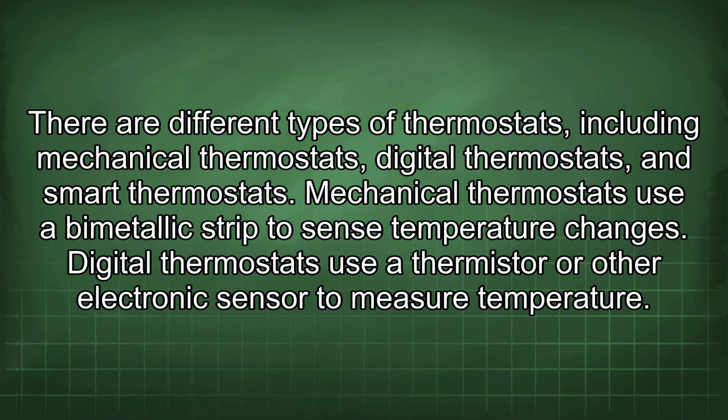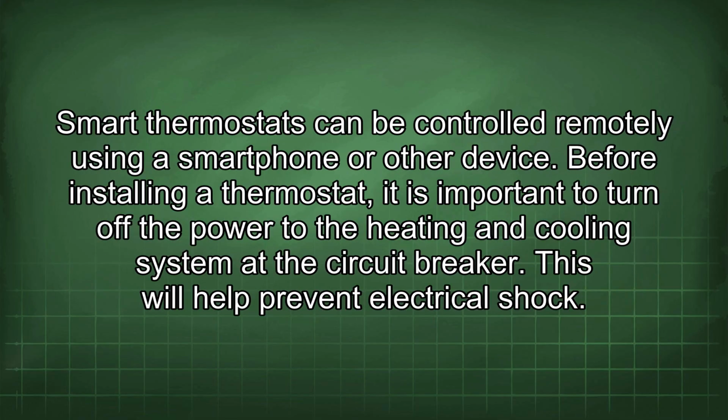There are different types of thermostats, including mechanical thermostats, digital thermostats, and smart thermostats. Mechanical thermostats use a bimetallic strip to sense temperature changes. Digital thermostats use a thermistor or other electronic sensor to measure temperature. Smart thermostats can be controlled remotely using a smartphone or other device.